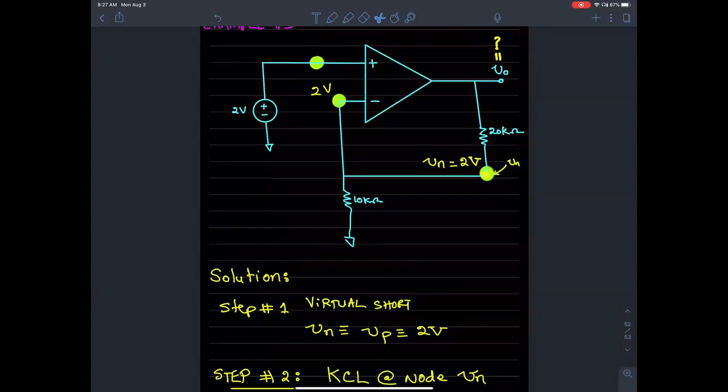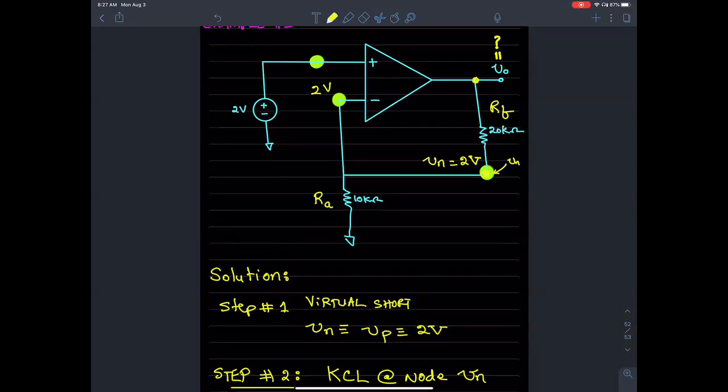So what is going on here is there is a feedback resistance RF through which the output is tied back into the negative terminal. Then there is RA, which is connected to ground. So it is still an inverting amplifier configuration, through RF, the feedback resistance, tying it back to the negative input terminal. So it really is nothing different from the configuration that we already know.